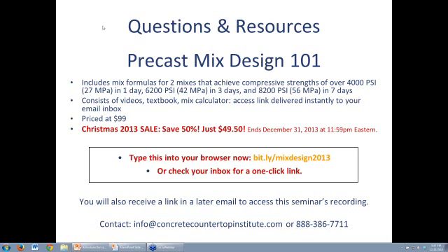So Brett, you've asked a couple questions. I'm using a white silica fume in my mix, so it's going to reduce your workability a lot and make it sticky. Do you think it is detrimental since it is white? No, if you know how to manage it, or if you physically know how to deal with it with superplasticizers. It's white because it doesn't have the irons in it that regular does. It has zirconia in it. That's what makes it expensive.